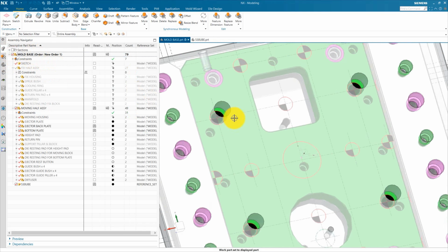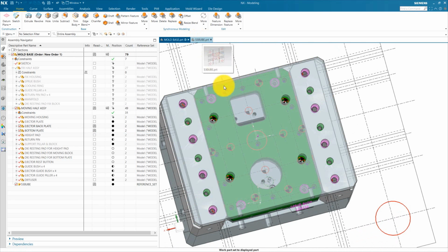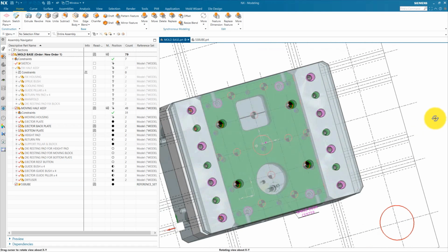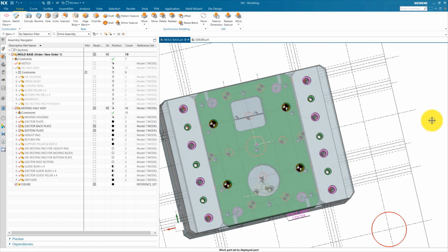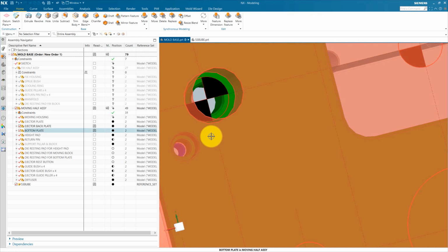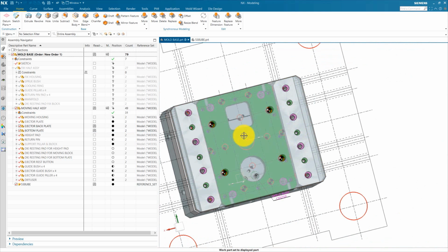Sometimes we add more ejector bumper rods. For example, this is for 530 machine tonnage. Some more ejector bumper rods are added in the same die according to 450 machine tonnage, so the die can run on both machines. So it depends upon your design and your feasibility study. You can add more machine tonnage inside this, and in that case you need to write here this hole for 530 machine tonnage, and maybe this hole for 450 machine tonnage. So we can write this here.